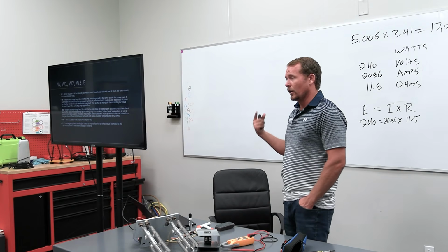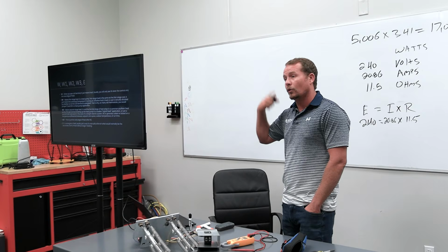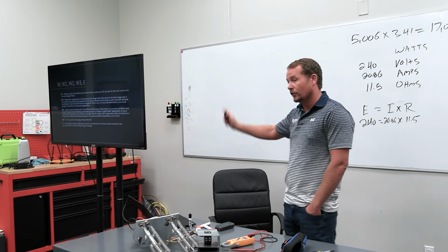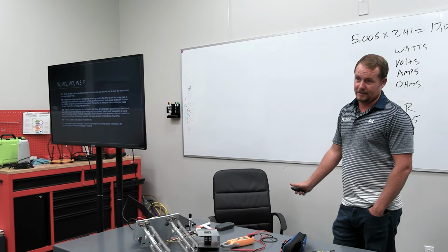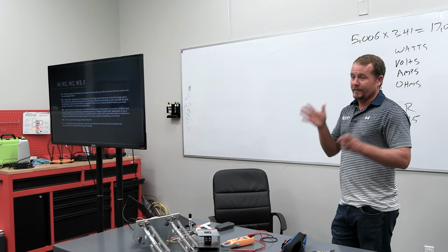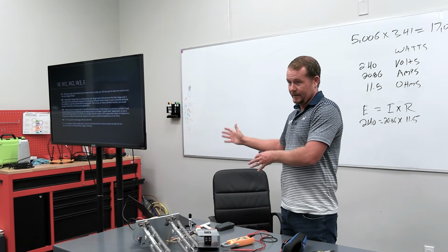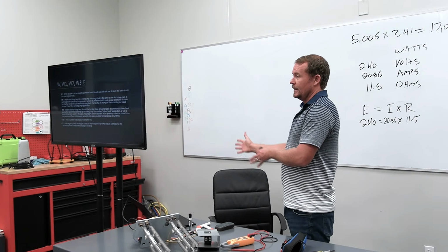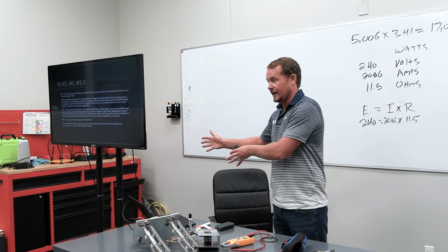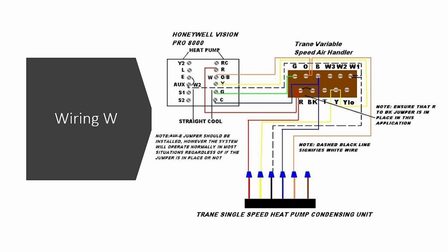But generally speaking, we're not going to use emergency heat much. In a market where you have very large heat strips, or in a market where one of your stages of backup heat is actually a gas furnace, well, now that makes perfect sense. Because there are markets, they call it hybrid heat or whatever, where you actually run the heat pump when the temperatures allow for it, and then you get to a certain point and you shut the heat pump off, you run the gas furnace. And in that case, if your heat pump's failed, you put it in emergency heat so it just runs the gas furnace. That makes perfect sense. Right? Make sense? Cool.